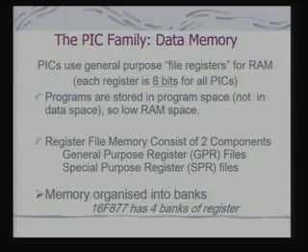Since programs are stored in program memory, typically you will find that the data memory is smaller, because the data memory is expected to be a scratchpad memory for temporary calculations and other things, and for storing the input data, if it is available.